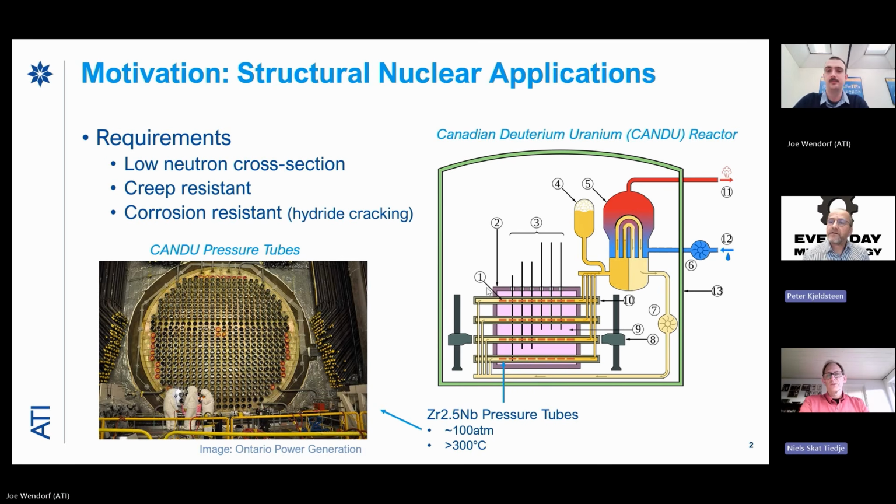Yeah. So, but you say the neutrons pass straight through the zirconium, but you still have a likelihood of some radiation damage to the zirconium. Yes. Is that right? That's correct. So nothing is 100% neutron transparent. There are still some neutrons that are absorbed. It's a matter of how many are absorbed. And then when a neutron is absorbed, you're exactly right. It can cause dislocations and vacancies to be injected into the material. It can also do some really crazy things called transmutation, where a neutron hits a zirconium atom and then it transmutes into another element, usually niobium.